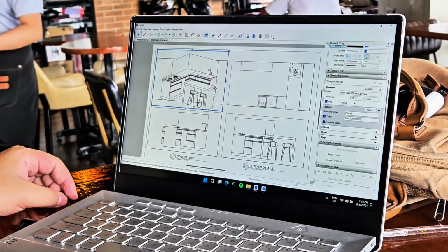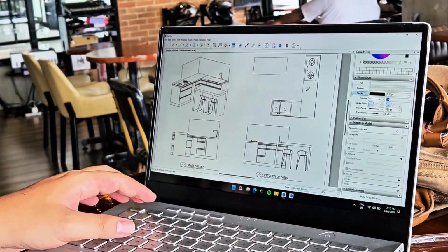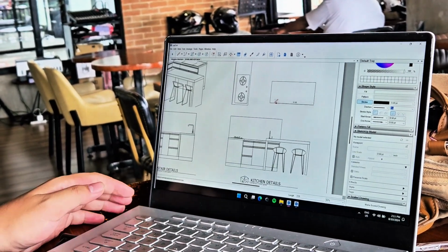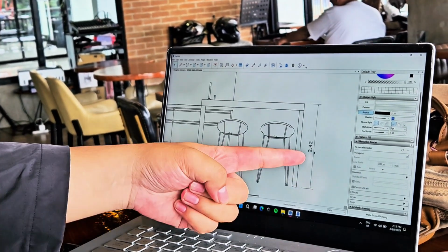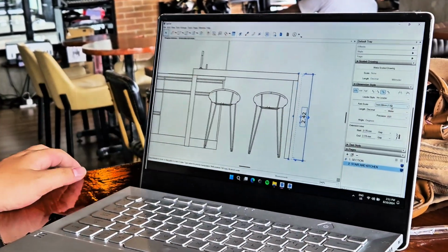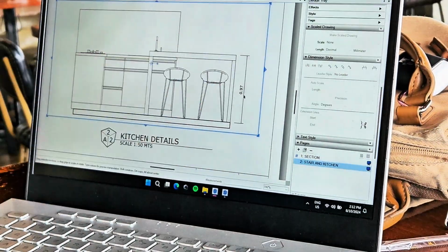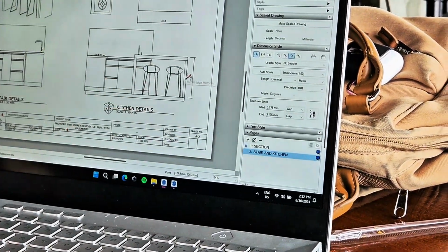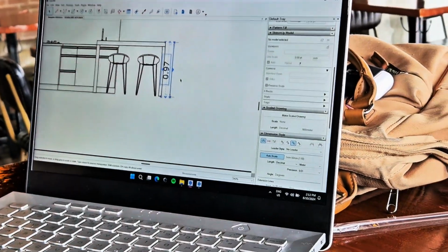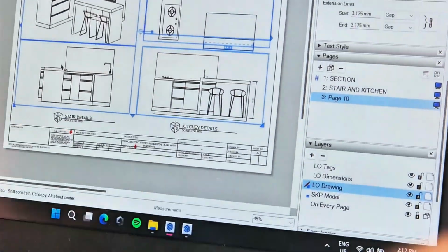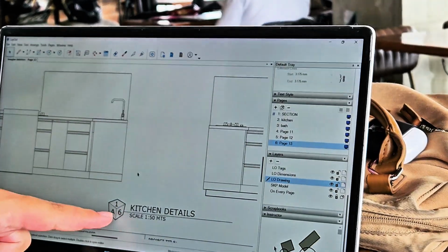Afterwards, I make adjustments so that the isometry can be seen even with the same scale. And then I try to align the top view to the front view so that the measurements that the carpenter sees will be aligned with each other and therefore more beneficial and efficient. Just make sure that your scale is auto scale so that the dimension will follow the scale of the viewport. If you want to force it to another scale, then you can turn it off and choose a specific scale. However, be careful when you resize. I then duplicate the page and then relink each viewport to another model for another detailed view.